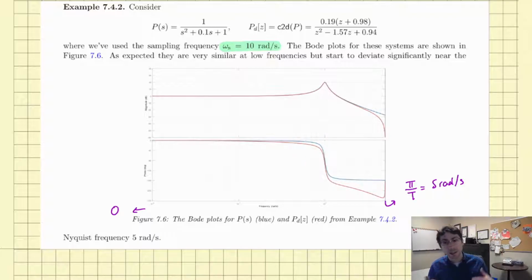And so again, if your control loop is going to be tracking signals of, say, 60 hertz, say you're doing a power application, you want to make sure you sample fast enough so that the Nyquist frequency is well above 60 hertz, because our rule of thumb is 5 times above 60 hertz, right? So this is just another way to think about conditions for choosing the sampling period.